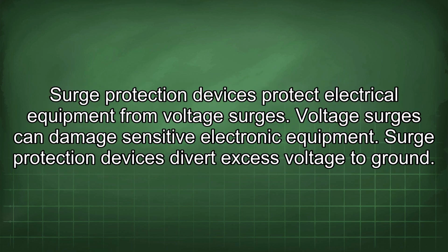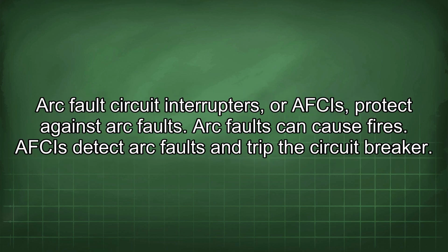Surge protection devices protect electrical equipment from voltage surges. Voltage surges can damage sensitive electronic equipment. Surge protection devices divert excess voltage to ground. Arc fault circuit interrupters, or AFCIs, protect against arc faults. Arc faults can cause fires. AFCIs detect arc faults and trip the circuit breaker.